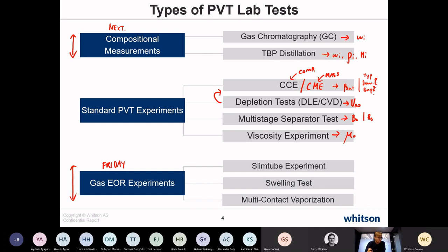I think I've heard about one guy, Rosbone, I think, who mentioned that he's seen a gas viscosity experiment done in the 80s one time. So for every single case, I think in the industry, the viscosity experiment is done for oil, while the viscosity numbers provided for gas are always calculated, typically from LBC or something.